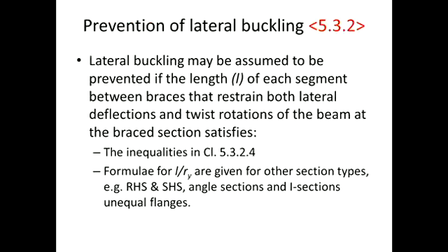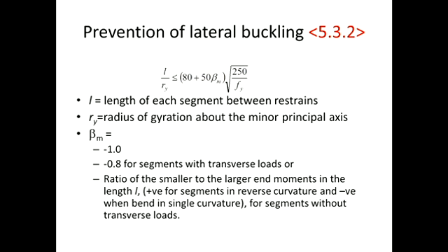So we can also have other sections, such as the rectangular hollow section or the square hollow section, if you refer to the standard in clause 5.3.2.4, then you can see the inequalities for all the other sections.